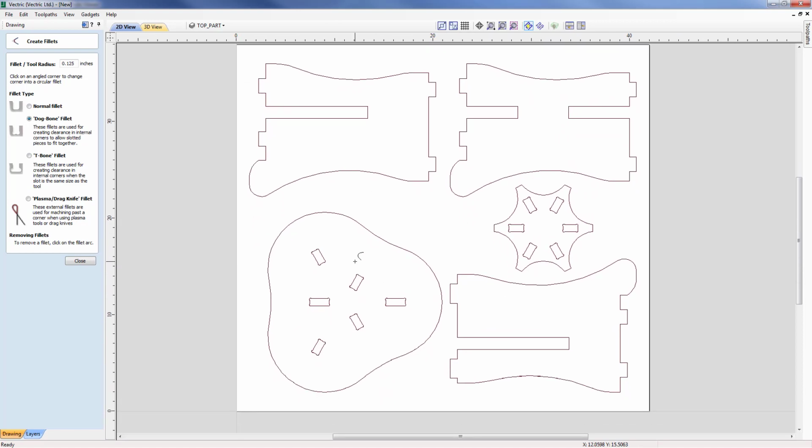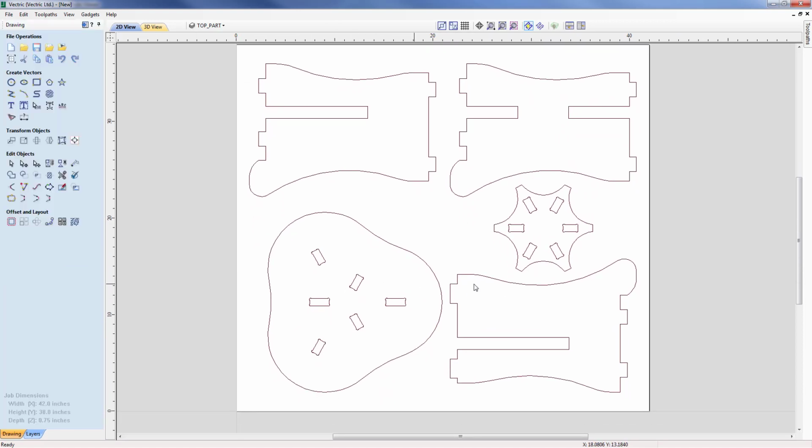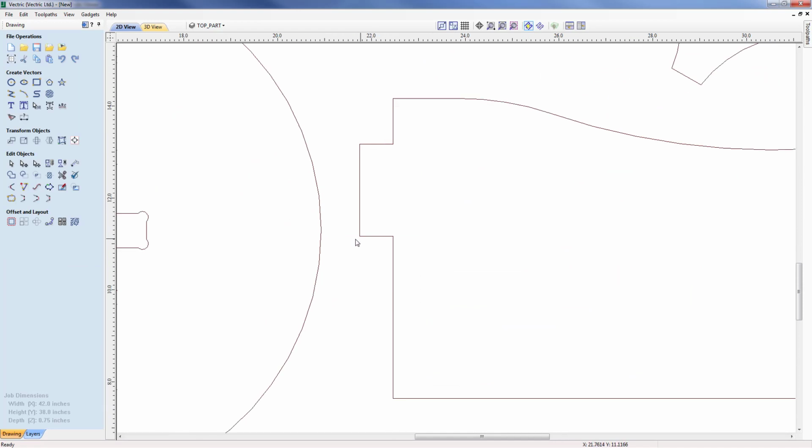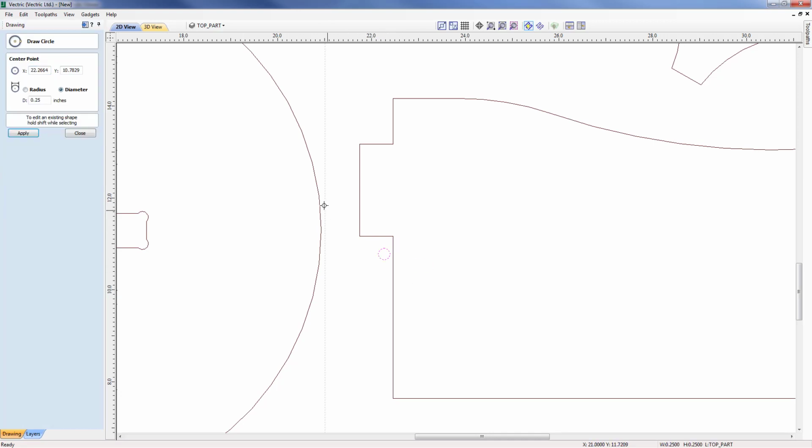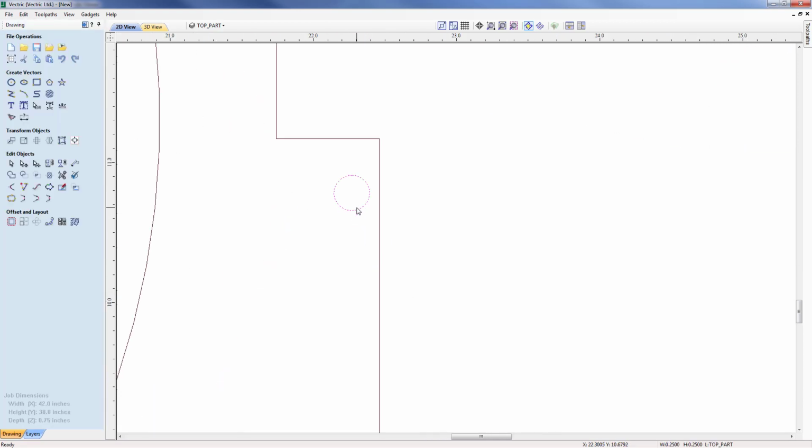Okay, so let's take a closer look at the issue that we're talking about here. We've got our 3/4 inch material here for our tenon, but of course we're going to be machining it with our radius, which if I place on the screen and then move into the corner, you'll be able to see we will be leaving a radius of material in that corner. We cannot produce a sharp corner with the tool wrapping around the corner. So what I need to do now is once again allow for that.